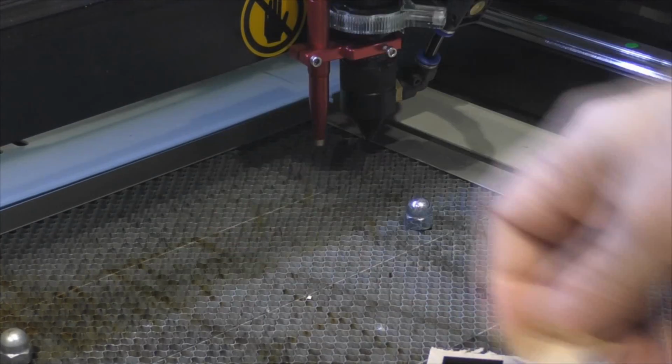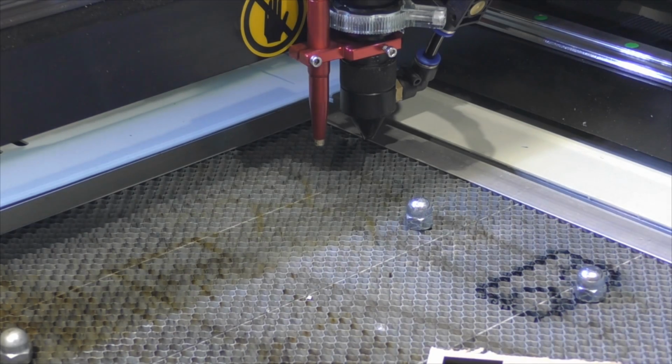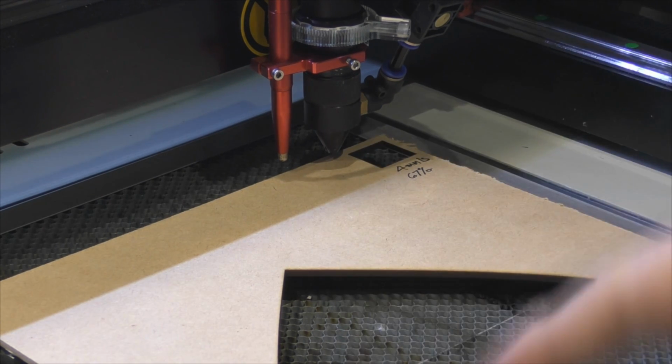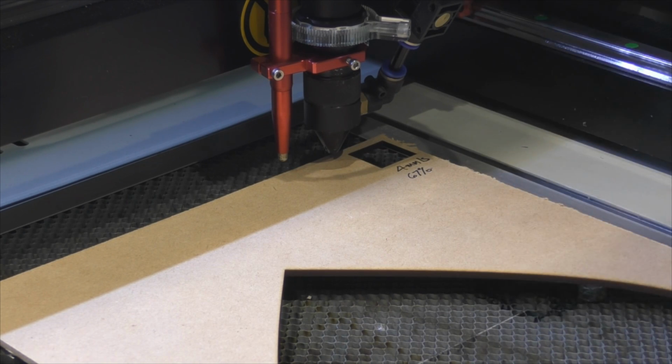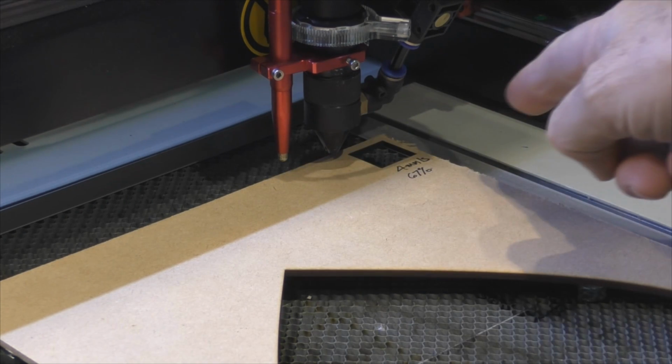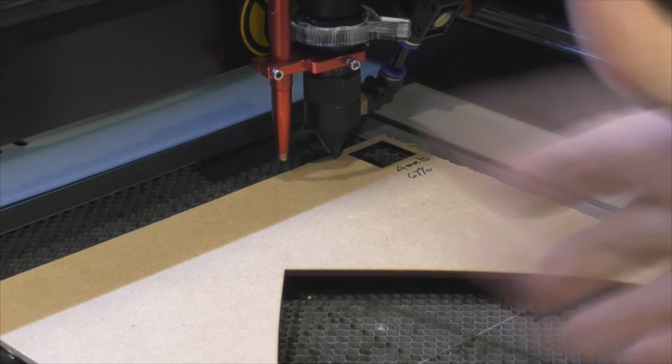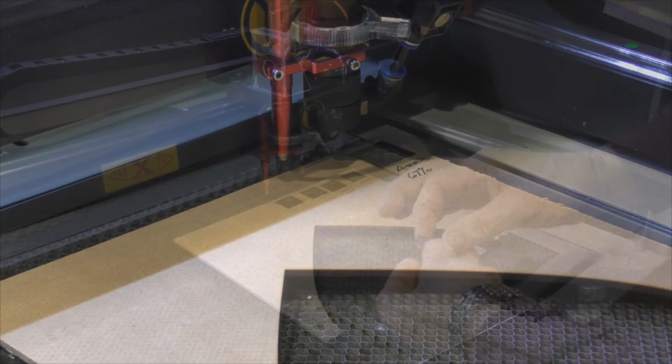Now, we will see what happens as we get a little bit faster. Let's double it. Let's go to 8mm a second. We could go up in single steps and spend ages doing it, but let's double it, because the worst that's going to happen is it doesn't work, and in which case we know that the good result is somewhere between 4 and 8. So we go through this halving process, doubling and halving, to get to a quick result.